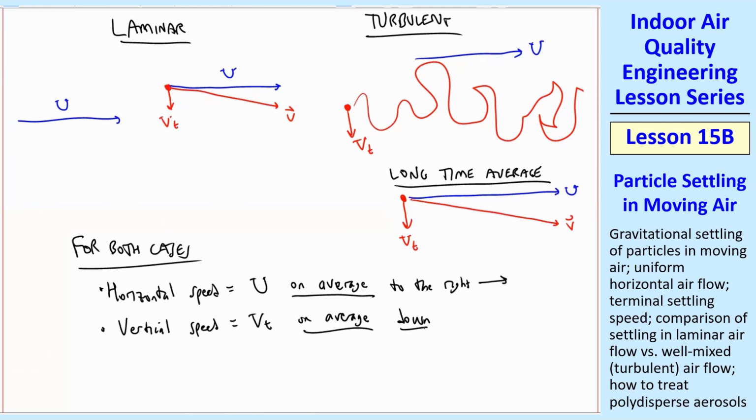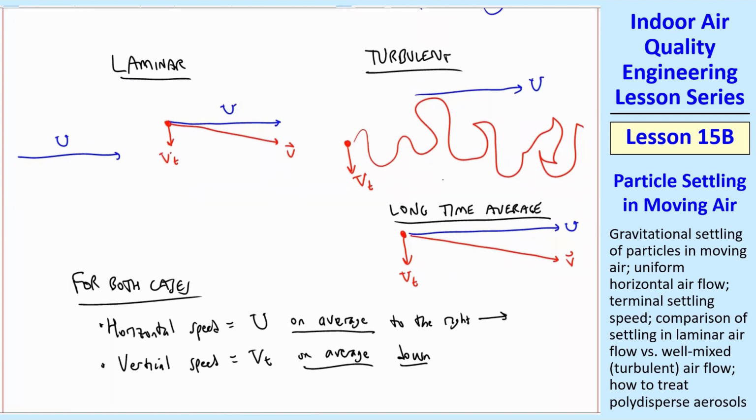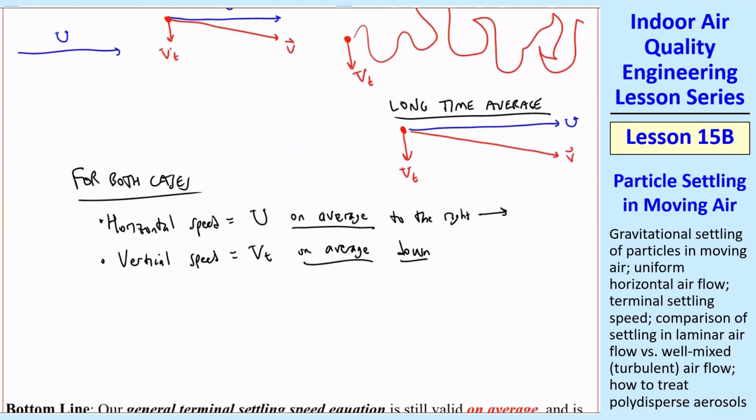So in our calculations, there's really no difference. I just wanted to mention, let's suppose there's some eddy in a turbulent flow like this, and you have a particle. Very small particles will move along with the eddy. Bigger, heavier particles will have some inertial separation, so they'll move like that. We'll talk about inertial separation later. If the eddy's that way, the big particles will tend to move out like this when there's no gravity.